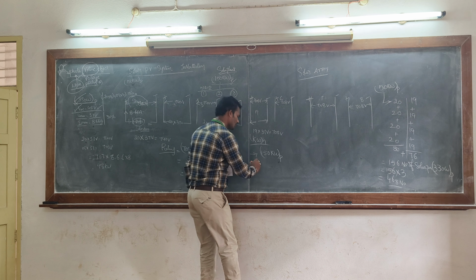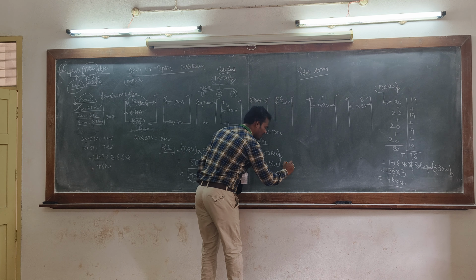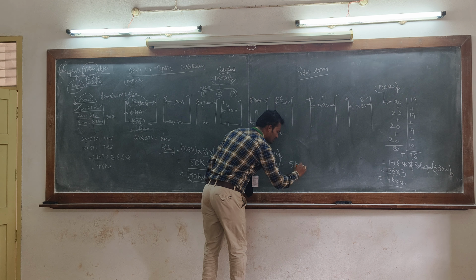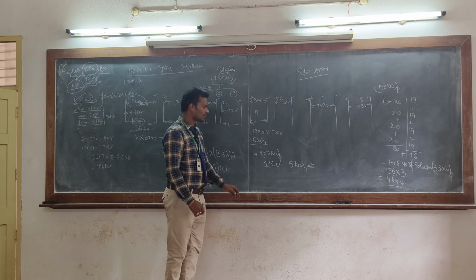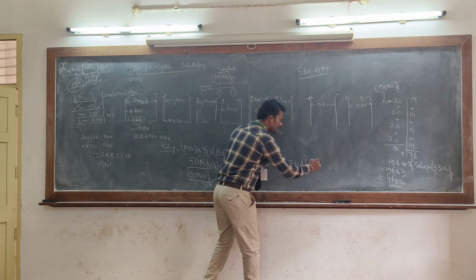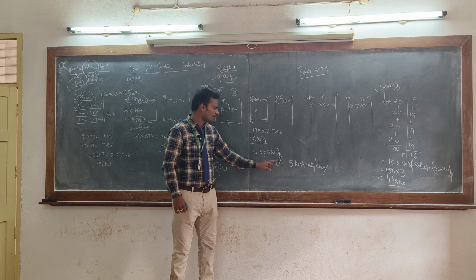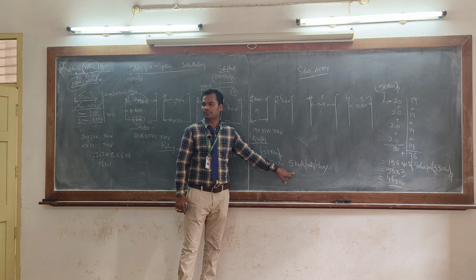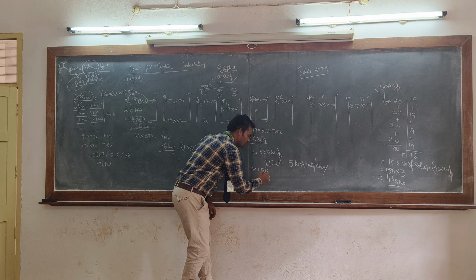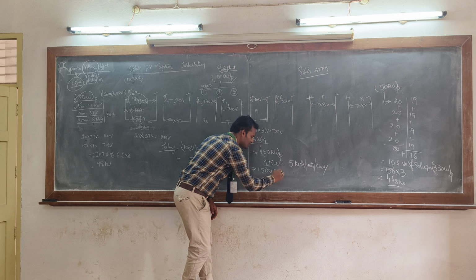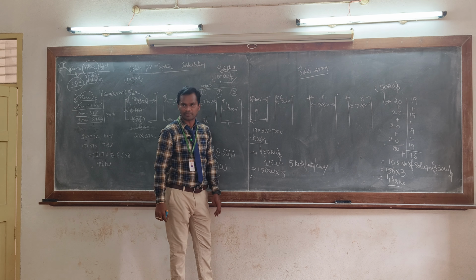As per the thumb rule, every 1 kilowatt plant will generate 5 units per day. So each kilowatt generates 5 units, and we have 150 kilowatt. Therefore 150 into 5.